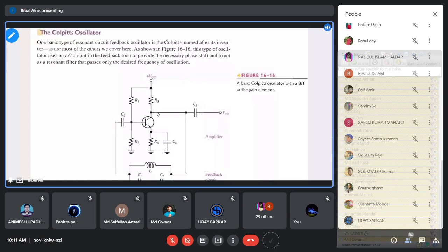There is a limitation, because the capacitor and resistance values that you can make restrict the frequency of oscillation at the output to low frequency, the audible frequency, less than 1 megahertz. That class of circuit, which is called the RC oscillator, cannot generate high frequency. RC means the beta network is composed of resistances and capacitances. That oscillator circuit cannot generate high frequency, that means greater than 1 megahertz.